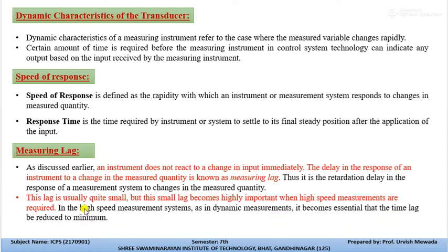This lag is usually quite small, but it becomes highly important when high speed measurements are required. Whenever we require a quick response of the instrument, this lag should be as minimum as possible, and from that minimum lag we can say the instrument sensitivity is very good, and it can be used for research technology, space technology or aircraft technology.